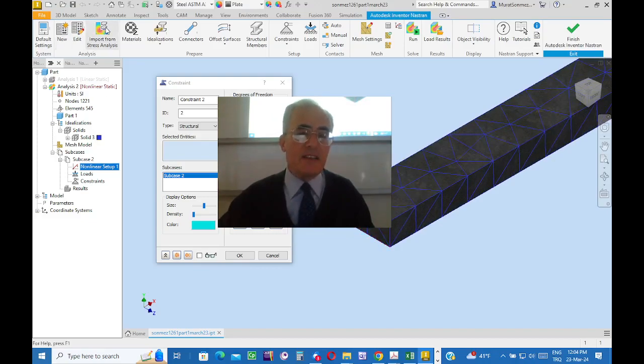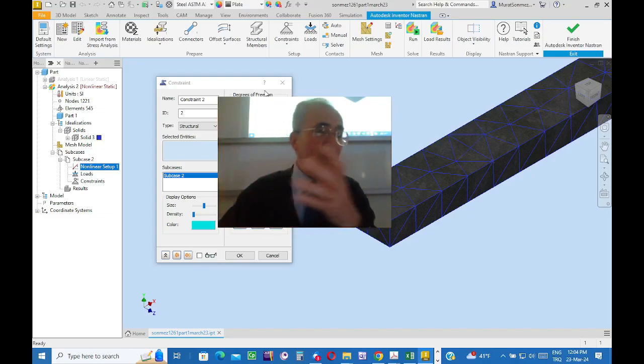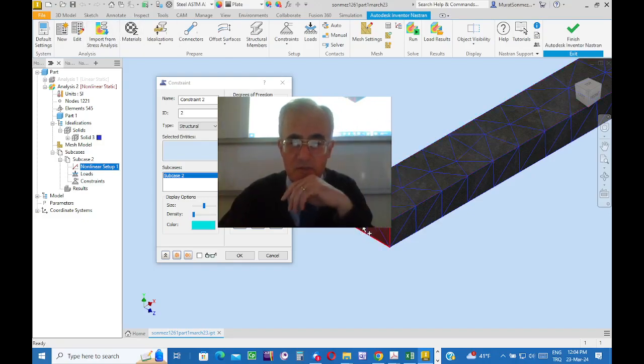Well, actually I forgot. If I had clicked on import from stress analysis, which has already been performed using the classical tool of Inventor, then not the results, but the boundary conditions would be transferred to the Nastran environment. But since I forgot to click on this button, it's not so difficult. I'm going to define the conditions. There are 2 conditions, not a time consuming thing.